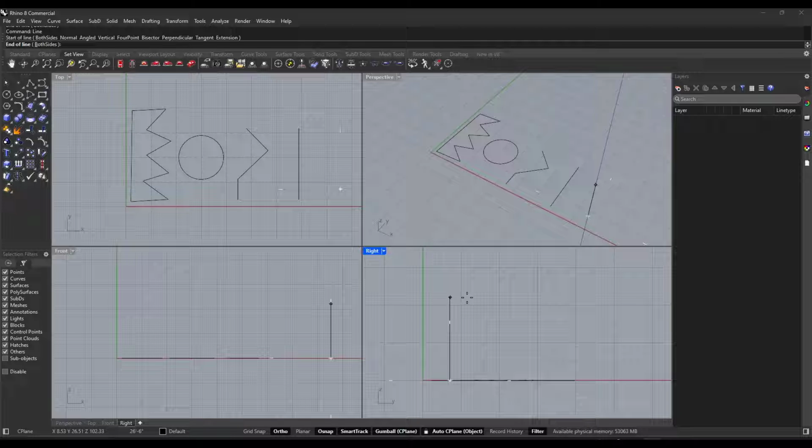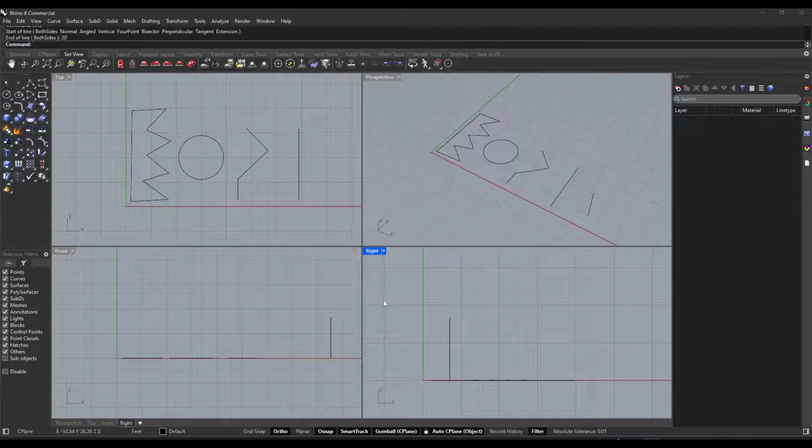So if I wanted to draw a line up that was 20 feet long, I could move my mouse over into this viewport, type in 20 feet, and hit the enter key like this. So you can use multiple different windows at once in order to do this. And so this can get especially valuable when you start taking shapes to 3D.